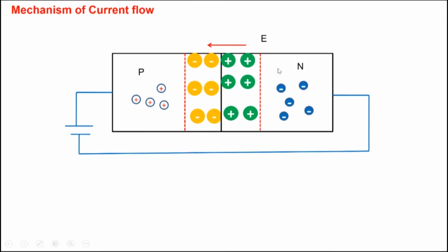When a hole goes over here and gets lost here, an electron-hole pair is generated at this particular point. So the number of holes is replenished. This extra hole comes in here. There was an electron lost from here, so there's a generation process. This electron then comes over to this side. And so you're back to the same number of holes, same number of electrons, but an electron has moved from here to here into this circuit, thereby contributing to current, which is in this direction, from positive to negative.